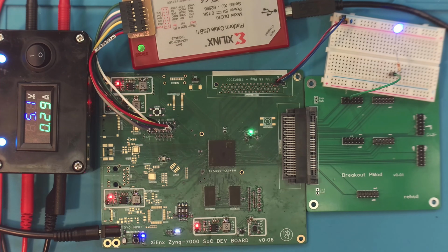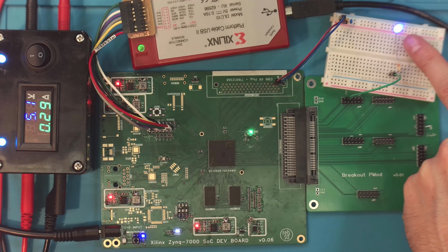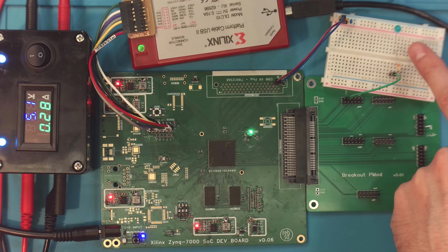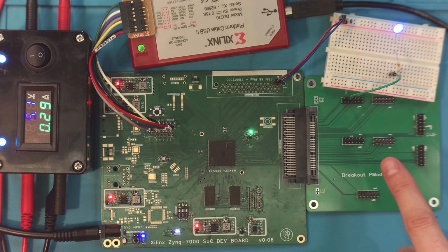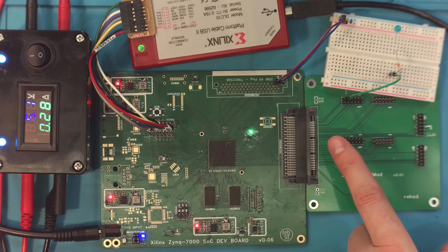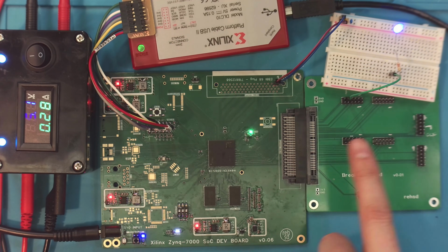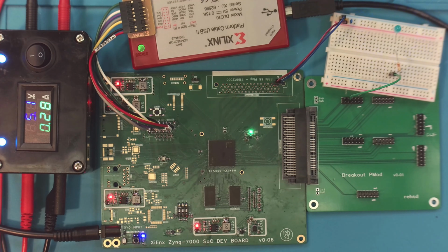up and running. So real quick, what I have here is an LED that's essentially connected through my tiny little circuit, but it's controlled through one of the ports on the processing system. I also have this LED that in the last video I did a simple FPGA fabric test on the programmable logic side. But now I am still connected to the same pin on the programmable logic side, but I'm controlling it from the microprocessor, the processing system here. So from my code, I am toggling both of these LEDs, and that is successfully working.